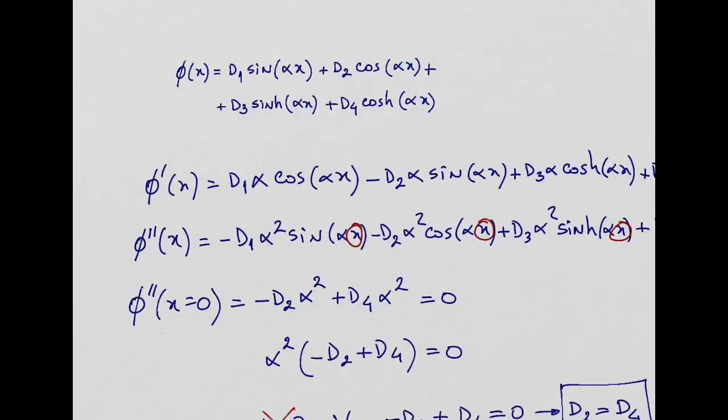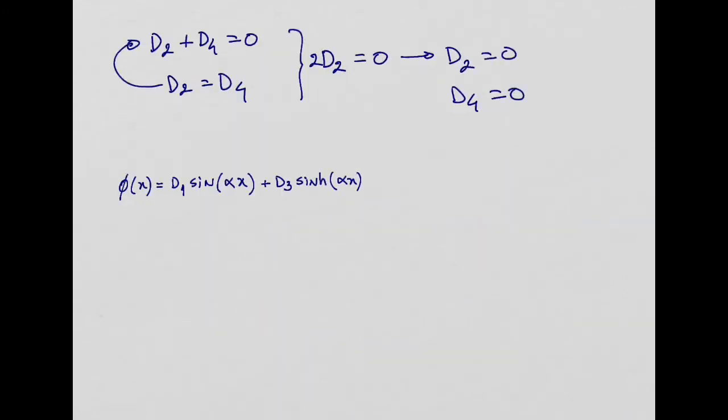So I need to now say that for x equal to L, so I am at the single support on the right hand side of my beam, I will need to have phi for x equal to L equal to 0, because the deflection at that point is not allowed as well.